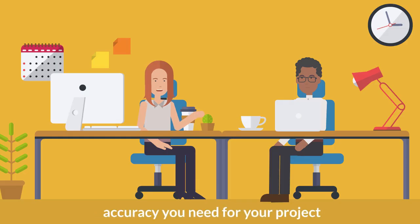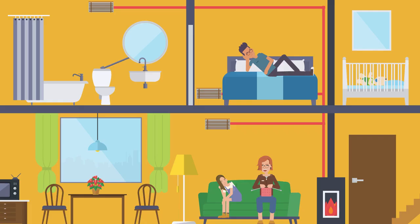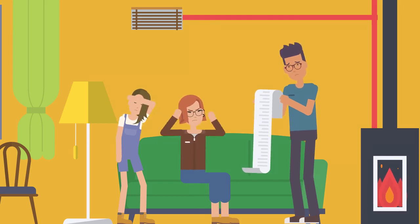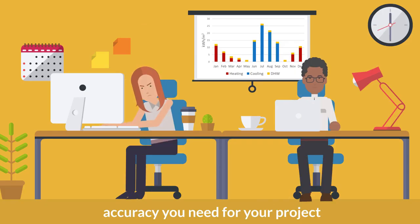The first decision you must make is the accuracy you need for your project. The higher the accuracy, the greater the difficulty of the calculations. When sizing the heating system, the goal is to supply all the energy that is needed when needed. Then, you may be tempted to oversize the system. The bigger the better. However, you should keep in mind that oversizing heat sources decreases the efficiency and the economic viability of heating systems. Therefore, you need a certain degree of accuracy to ensure the realism of your design.